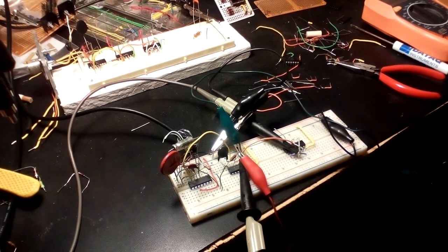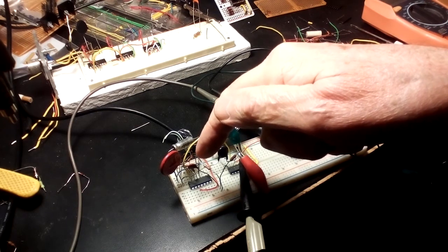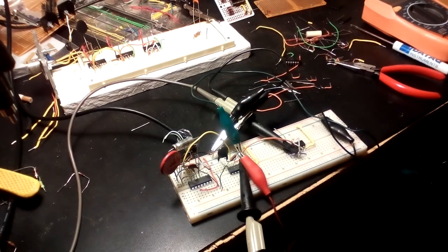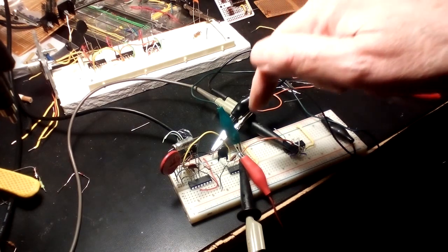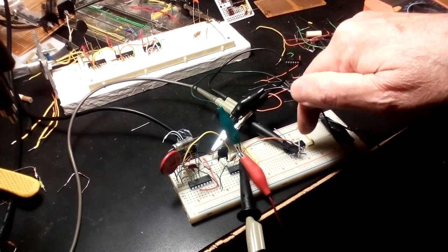Okay, here's what it looks like. This is the AC times 10 channel. Not much to it. You can see it gets a little busy up here around the comparator. I probably ought to build a PC board. We'll get around to that. My breadboards are concept development. They're not really prototypes or production models, for goodness sake. It's kind of Rube Goldberg, but the only important thing is they work. This is the dual flip-flop package, and this is the ring oscillator.